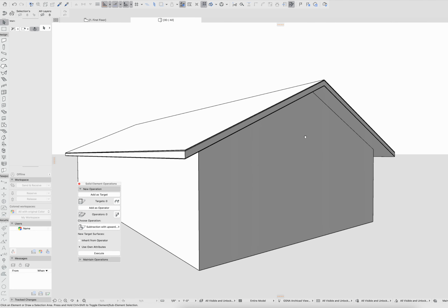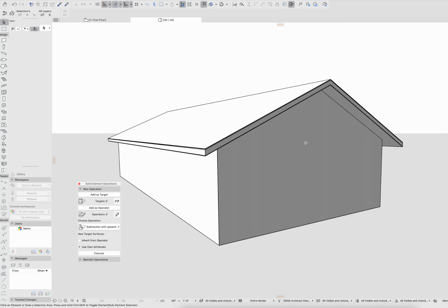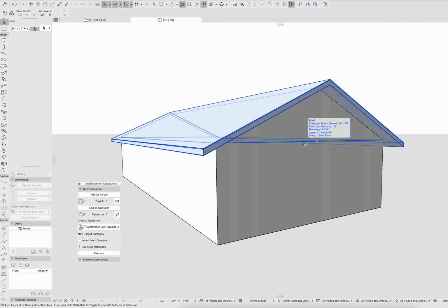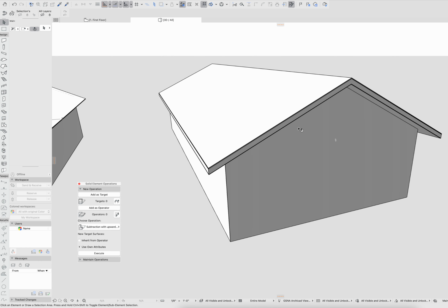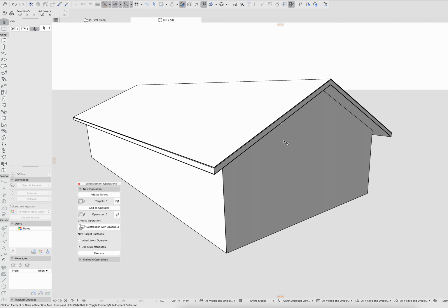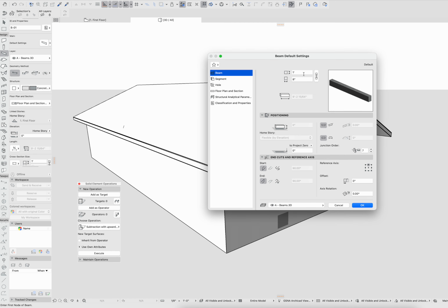All right, I want to expand on the video I did the other day about roof and trim using complex profiles. If we have a situation where we have gable ends, there aren't hips and valleys, and basically eaves all the way around the roof. We have conditions where there are gutters and bar rafters, sort of gable end type stuff. I don't usually use a single profile. I'll use something like a beam for the fascia, a beam for the bar rafter.